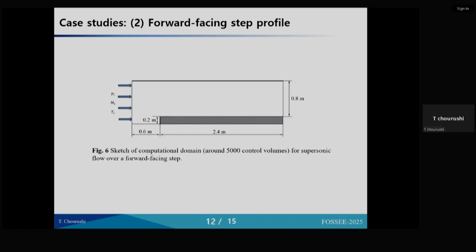Now, you can further extend these high resolution schemes to another class of fluids, the compressible gas flows. The domain you can see here is a forward facing step, wherein the compressible gas is entering, and we have a wall present at the top. At the outflow we set a wave transmissive condition, and if you are using OpenFOAM, you should be careful with that. Here the highly compressible fluid is entering with a Mach number of around 3, so it's a supersonic flow.